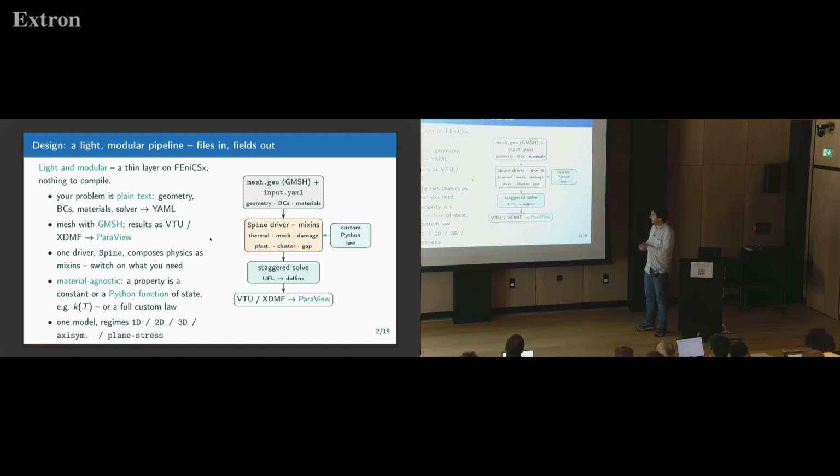I have a couple of scripts that start by reading some input quantities that for me are, but for everyone, I guess, are a geometry, a mesh. And then I started collecting input settings, let's say, to start a simulation in a YML file, collecting solver settings, boundary conditions, material properties, and so on.